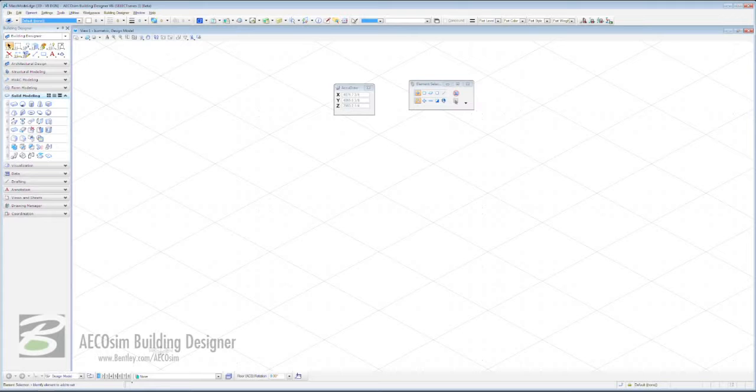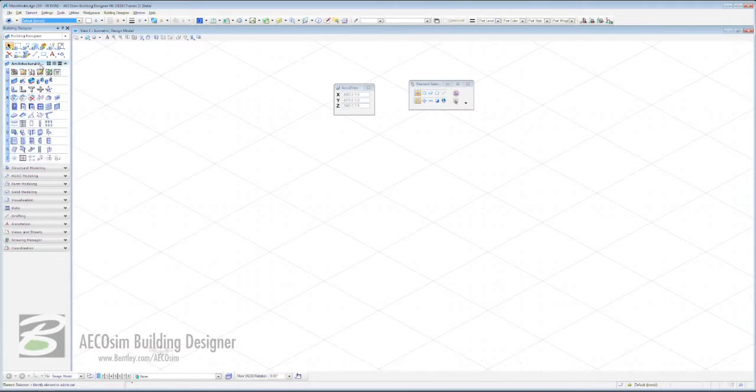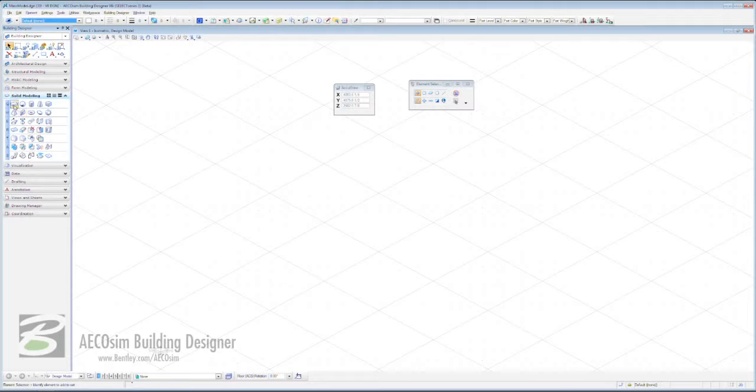We then have our primary building toolbar here, and this contains our families and the parts within them, as well as all the other controls that we may need. And then we have our locks across there. But the real heart of Building Designer, on the left-hand side by default, is our task-based interface, which contains every single design tool that we'll need in our building information modeling in very efficient and handy collections of tools for specific reasons. So with that, let's go and start modeling, because we want to open up our solid modeling tab here, and we want to come to the first icon, first row, slab solid.